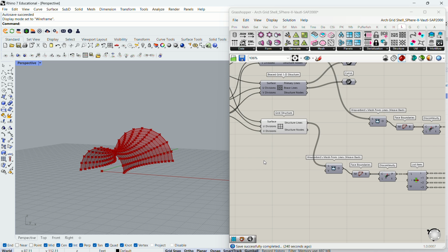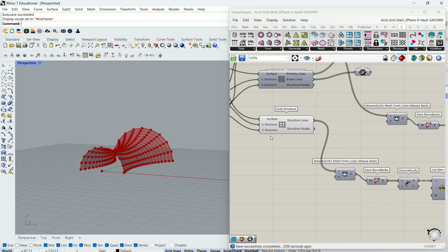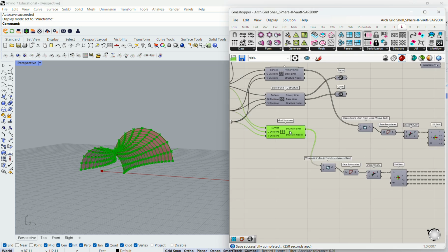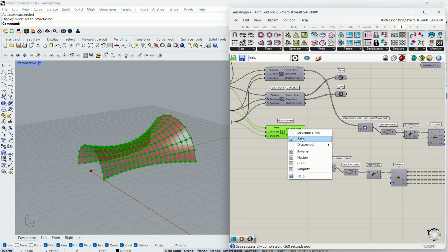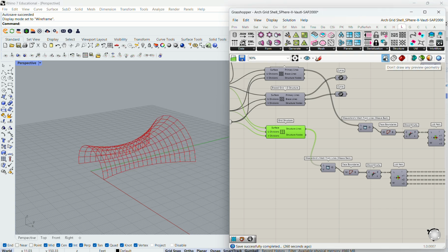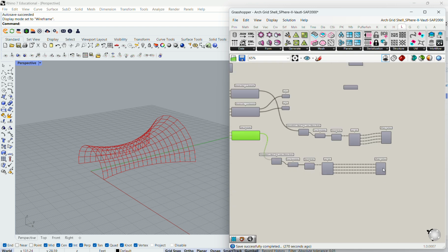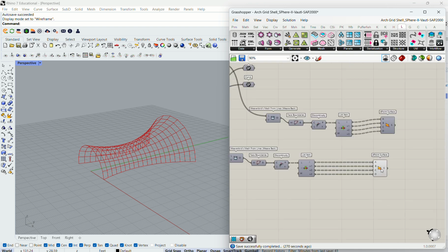Let me see. Maybe I can bake both together and import to SAP together, so I can show you both comparisons. First, I need to bake, meaning obviously I need this geometry. Right click and bake, into layer 1. So basically I have a line here. I'm using feet, so you need to follow along. And also this, because I need some surface in order to assign the area, the wind load, and also the estimation for our cladding weight dead load.